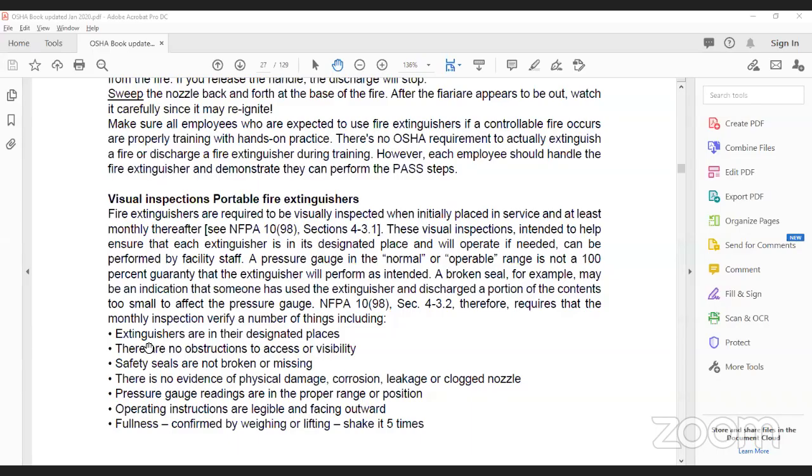Right. According to our book, there are some principles and rules for how we can inspect them. Basically, there should be an annual maintenance record, and even a monthly inspection for these fire extinguishers, as they have inspection dates and even expiry dates. First, I will share the picture. What you should check first: the pressure gauge and the pin.